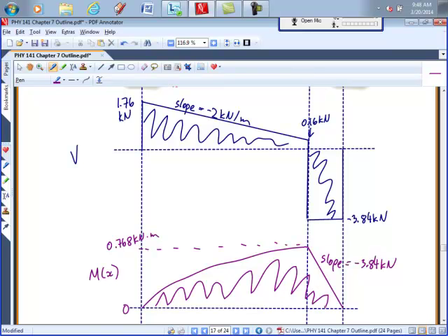But from the moment diagram, and some properties of the shape and of the material, the modulus of elasticity and the moment of inertia of the cross-sectional area, we would get an angular deflection from the next integration, and then we would integrate it another time to get the actual displacement.